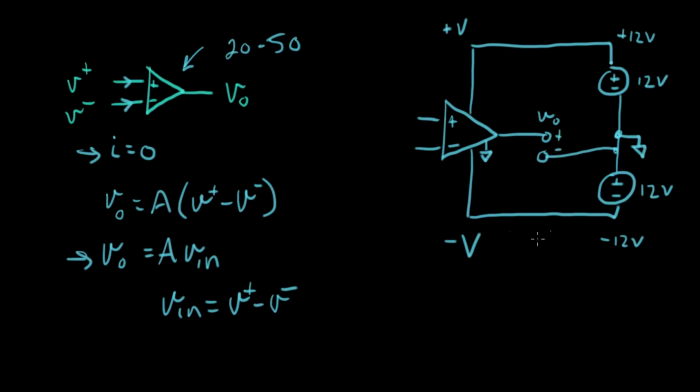What we're going to do is assume that all of this stuff is always hooked up, and we're just going to use an even simpler symbol, just the three terminals, like that. And you'll know that all the rest of the power supply is hooked up that way. The thing to keep in mind is there's a large minus voltage, there's a large plus voltage, and the ground node is right in between. So positive voltage is high on the page, negative voltage is low on the page, and V out can go both positive and negative around ground. So that's your voltage framework to keep in your head.